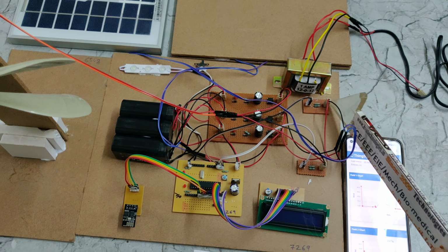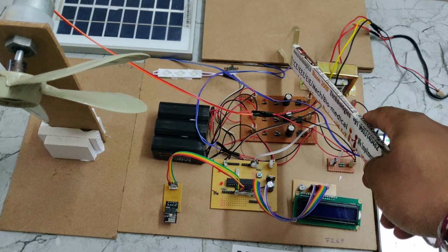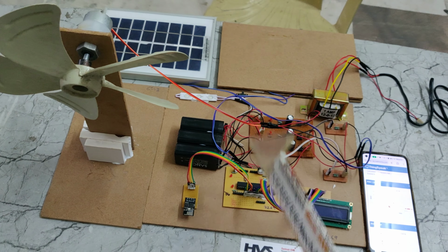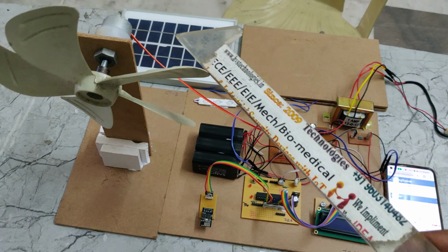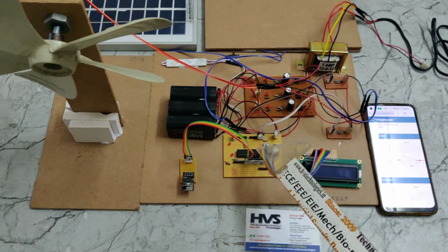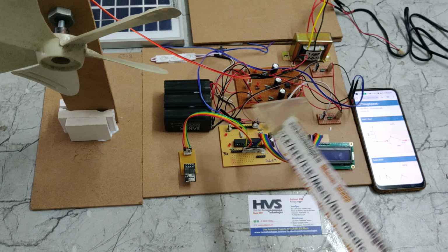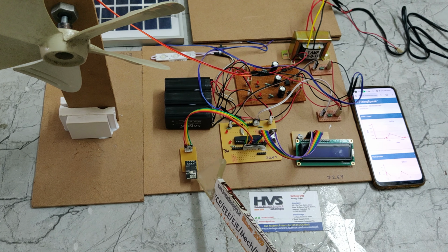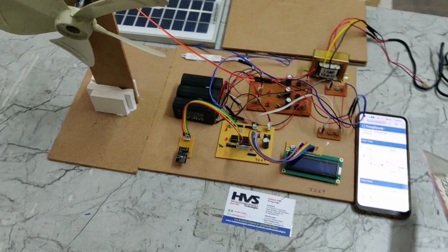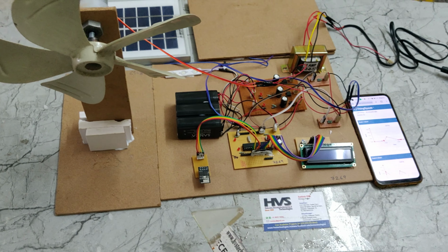And here we can see that two voltage sensors are placed. The piezo directly interfaces to the microcontroller, as it provides low current. That's why we need to interface it directly to the microcontroller. The interfacing is A0, A1, A2 pins for the respective voltage measuring purpose, and B2 to B7 interface to this PIC microcontroller. B0, B1 are for the ESP8266 Wi-Fi module. It's continuously uploading to ThingSpeak with the help of this ESP8266 Wi-Fi module.